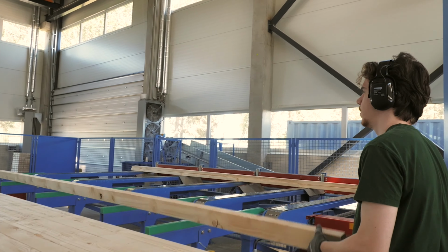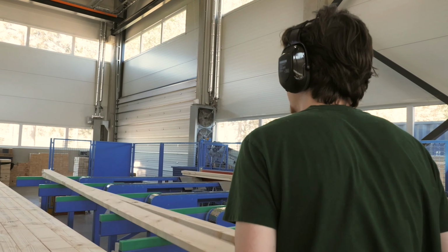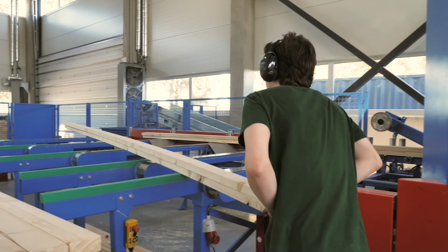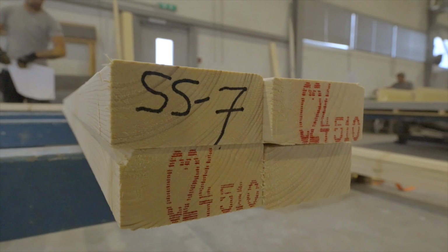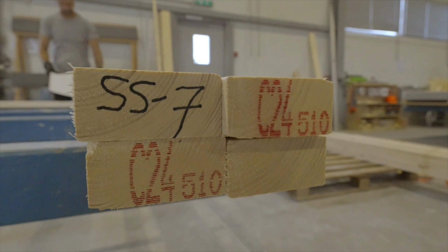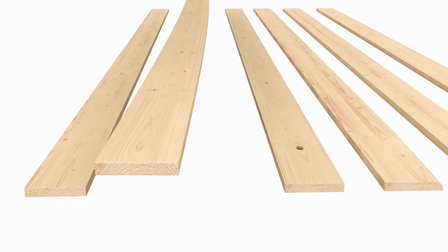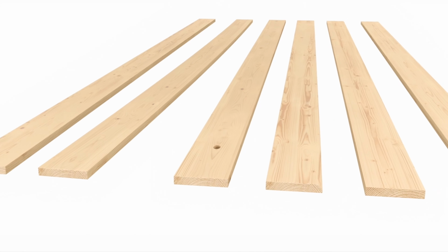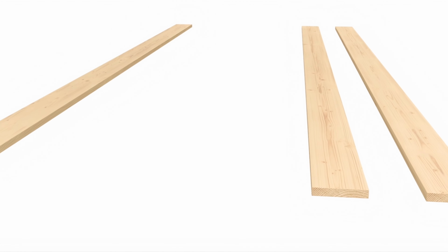Before starting to assemble the elements, it is necessary to visually check the quality of the material, as well as its compliance with the drawing. The timber material of the load-bearing structure must be strength-sorted and have a designation indicating the strength class. Usually it is C24. If the wood is visibly curved, has through knots or wane, then this material must be placed separately from the others, in a place designated for the defective material.